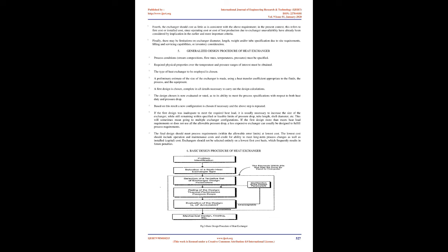Heat exchangers in general and tubular heat exchangers in particular undergo deterioration in performance due to flow maldistribution. The common idealization in the basic tubular heat exchanger design theory is that the fluid is distributed uniformly at the inlet of the exchanger on each fluid side throughout the core. However, in practice, flow maldistribution is more common and significantly reduces the idealized heat exchanger performance. 1 shell pass and 1 tube pass. Fig. 1-1: 1 shell and 1 tube pass heat exchanger. Fig. 2: Shell and tube heat exchanger.